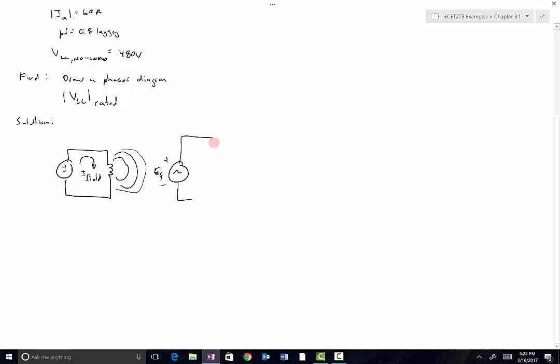Part 2 is that there's a circuit model for the armature. That is that it has a synchronous reactance X sub S associated with it, and it has an armature resistance R sub A associated with it. So the voltage here that I'm indicating is often called the terminal voltage of the generator, and this is the phase version of what's actually measurable at the output terminals of a generator. So you actually really can't measure this internally to a generator because of these.